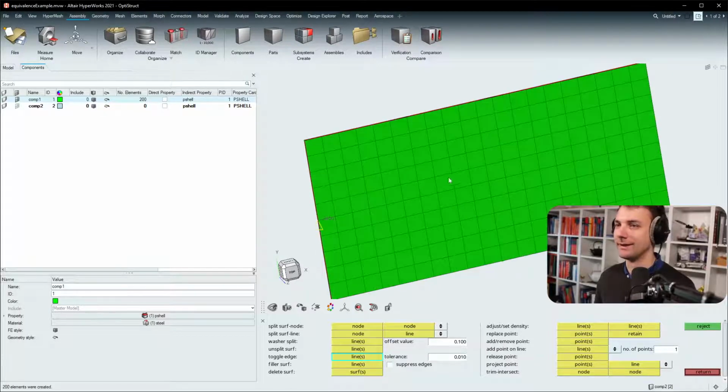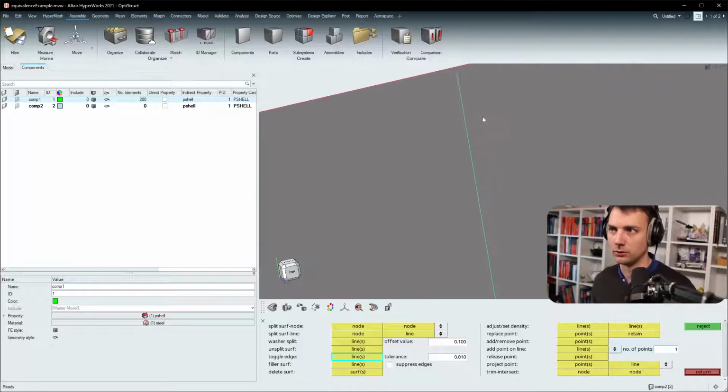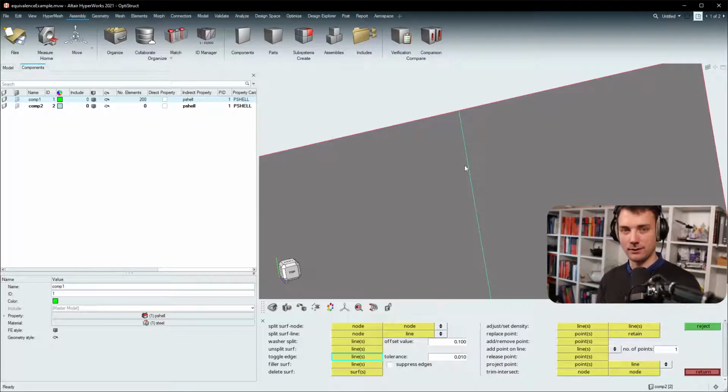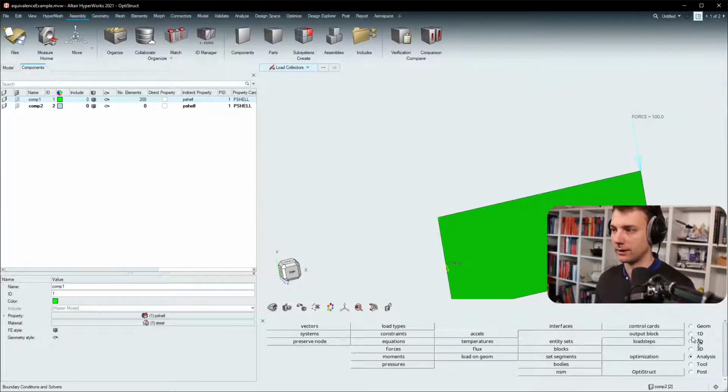Oh, now the mesh is back because I suppressed it, right? So left click toggles the edge, then it was green. And now clicking left once more suppresses the edge, which means it's now blue dotted, which means that this line has no effect on the meshing. You can see that if you do a tetra mesh, and not a tetra, a triangular mesh.